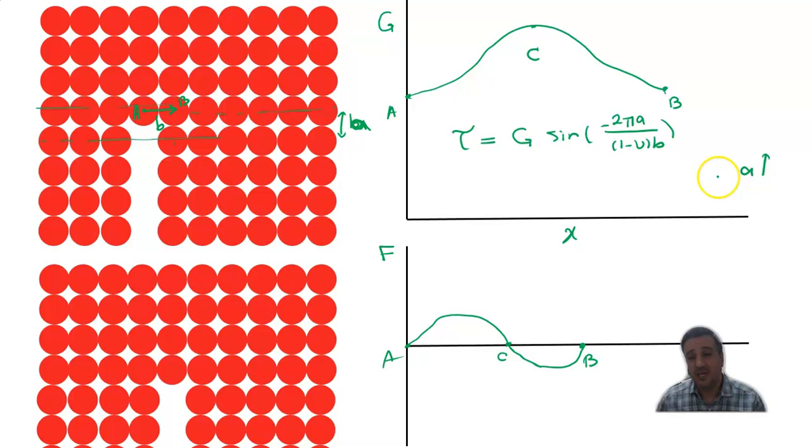So we can conclude from this equation that the slip of the crystallographic planes is easier in the planes that are farther from each other. For example, in the FCC crystal, the {111} planes have the highest distance with respect to each other, and that is why these planes act as slip planes in FCC metals.